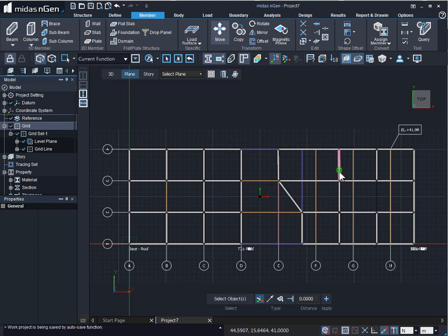For example, we are wishing to move this particular object, and this object we want to move in this direction itself, but I changed my mind and I would like to reverse the direction. So by clicking over here, we have reversed the direction, and now instead of going to the left side, it's going to the right side. And then we can apply.